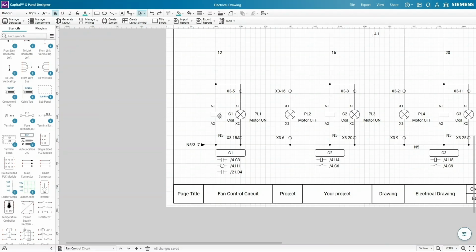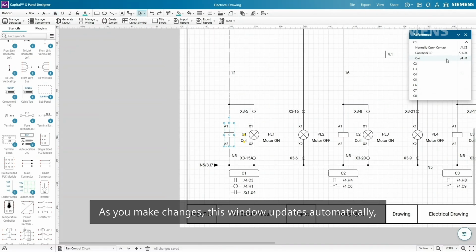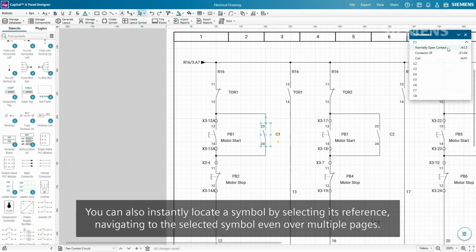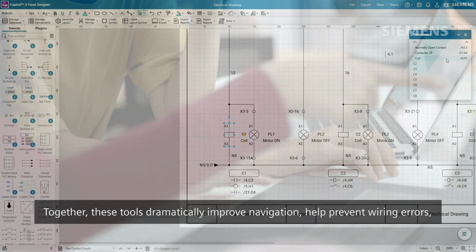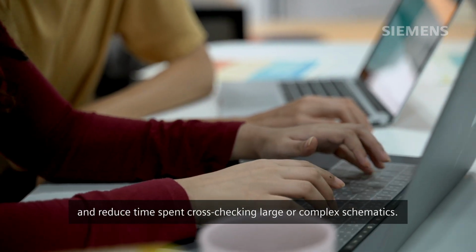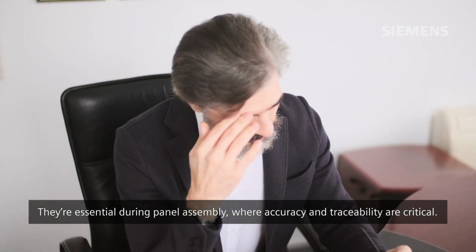Another cross-referencing tool we have in Capital X Panel Designer is the Real-Time Reference window, which provides a centralized view of all symbol references. As you make changes, this window updates automatically, adding new references when symbols are placed and removing them when deleted. You can also instantly locate a symbol by selecting its reference, navigating to the selected symbol even over multiple pages. Together, these tools dramatically improve navigation, help prevent wiring errors, and reduce time spent cross-checking large or complex schematics. They're essential during panel assembly, where accuracy and traceability are critical.